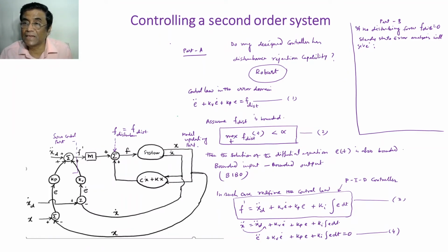If the steady state error is 0, you will feel very comfortable, meaning it is exactly following the trajectory. So steady state error analysis is analysis corresponding to a virtual static state. Means in the dynamic equation, if you make all the time-related terms 0, then what error remains will be the steady state error.